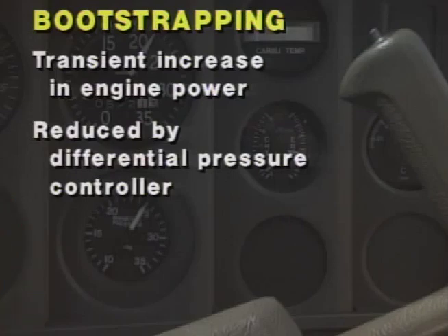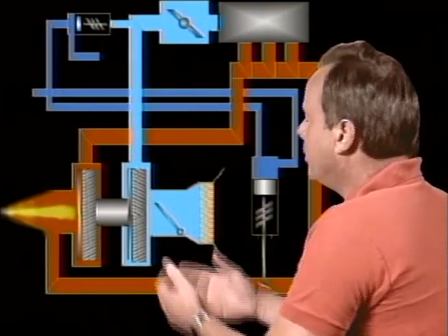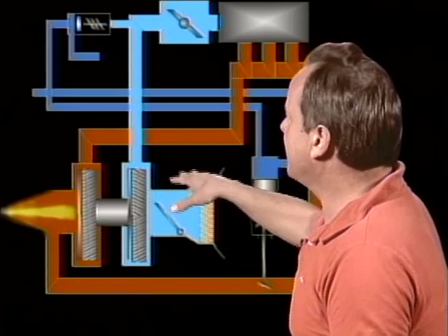A turbo-normalized system is one in which you just keep ambient manifold pressure at sea level all the way up to higher altitudes. It makes the engine think it's at sea level even though it's really at a higher altitude. Now, there is a different set of controllers in that engine then.